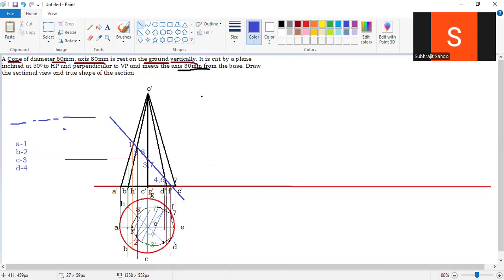Observe, sir. The 45-degree angle is set in the drafter. Insert in the drafter, then draw the hatching line. Already told what the condition is. The gap should not be more than 2. The 45-degree angle should be maintained. All these are restrictions, strict rules for this, right? Hatching line 45-degree you have to do.